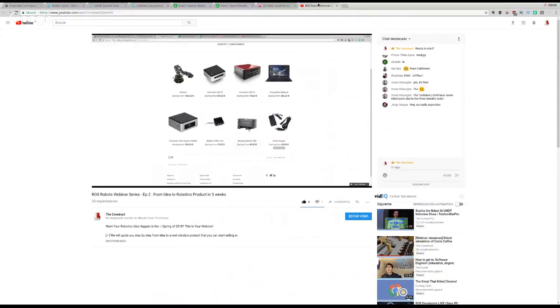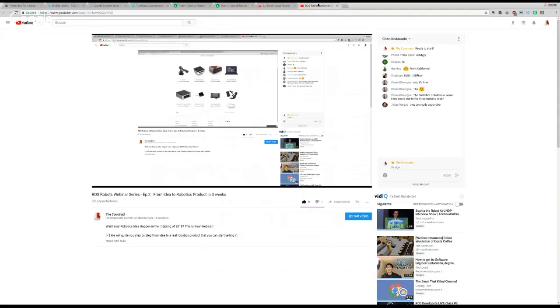And in the meantime, I'm answering some questions here. Biorel says the Turtlebot LiDAR has some blind spots due to the 3 metallic rods. And the answer is yes, but they are very, very small blind spots. How we did it is we take the laser and just filter the measures on the rays that are colliding with the metallic rods.